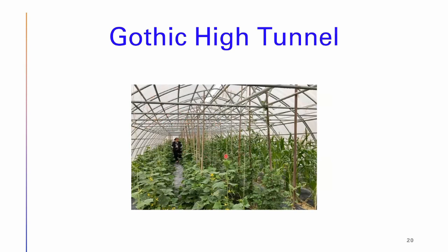So this is 2 years ago. My wife was in here. This shows mid-season and after we started growing in it. So it's a very practical greenhouse. It's 12 feet high. And the thing is, because it's on purlins, so if you look here, these are square tubes, 14 gauge galvanized tubing on 2 to 2.5 foot centers. And I think there's 4 foot centers at the bottom.